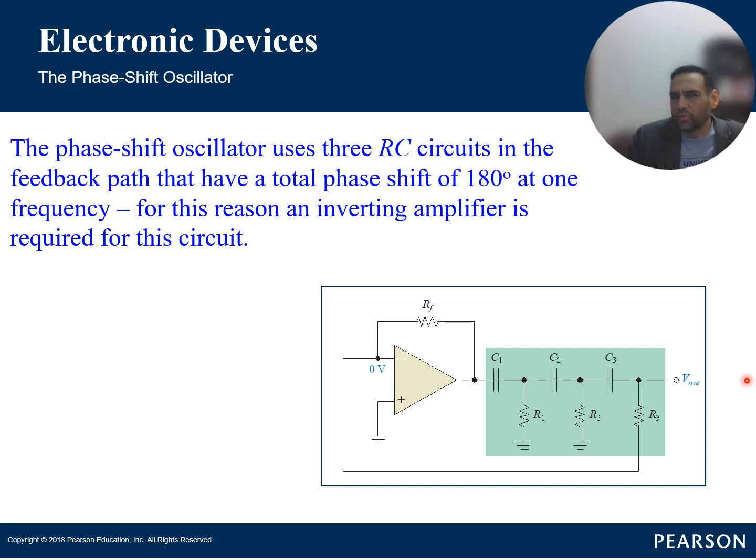If you do this in simulation and you see nothing, read the lab procedure again, because you're probably missing a step there to create that disturbance artificially. In the practical breadboard circuit, some small noise or disturbance is enough to initiate the oscillations. The circuit starts into its oscillation and then goes into a stable oscillation mode.